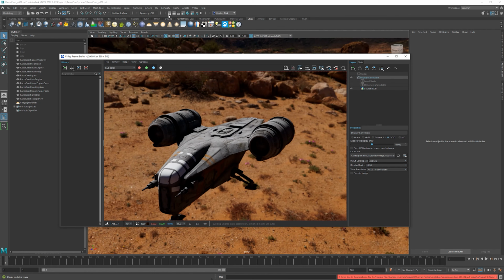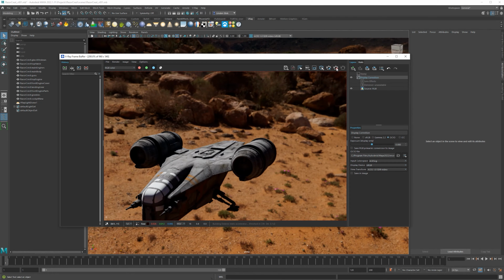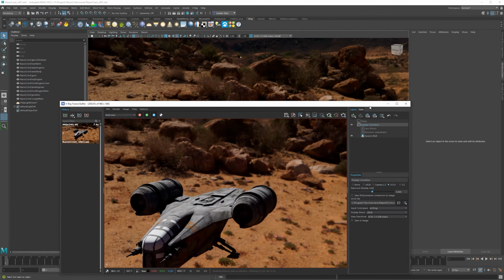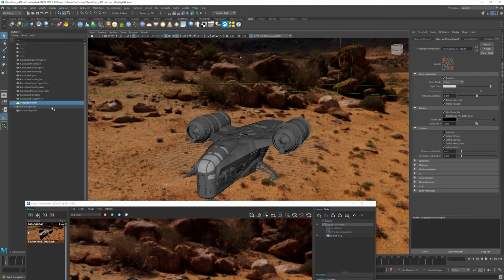And then this button right here doesn't actually open up the V-Ray IPR. It is just this button. So if you want to open this up and not render it, you've got to open up this right here. All right, so we're going to actually stop that, move this over. There's a couple things we have to do here on the dome text.